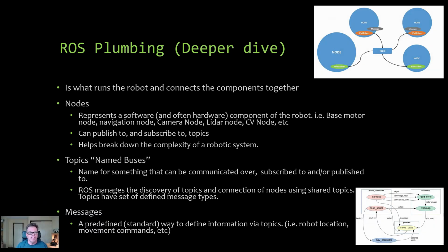Okay, the next ROS plumbing component is topics, and they're also called named buses. An easy way to think of them is as a name for something that can be communicated over, subscribed to, or published to. Topics are set up so that nodes don't need to be aware of other nodes. They just talk to topics or listen to topics, and they can do that independently of other nodes. So it makes it easy to swap out nodes.